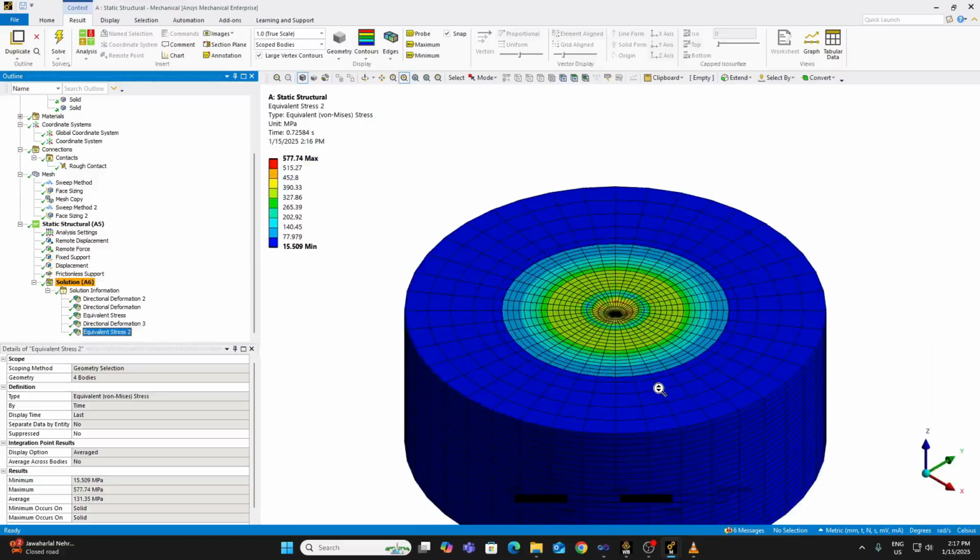So I think I'm mostly done with this particular simulation. Okay. The assignment for you would be to try this particular simulation as well as the simulation of tensile test using number one, an axisymmetric model, and number two, a cyclic symmetric model. Okay. Both are quasi-static analysis, and for quasi-static analysis, cyclic symmetry can very easily be defined by a set of boundary conditions. But also you can use the cyclic symmetric tool that is there with Workbench. Okay. And you can find that from Ansys help doc or YouTube videos, so you are free to do that.